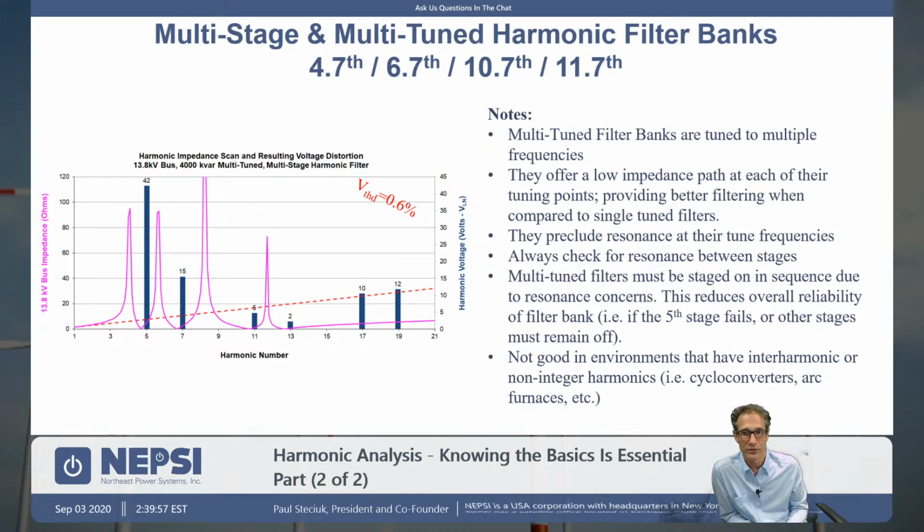It's important that you design reliable lower frequency filters because the loss of one of those could result in the complete shutdown of the harmonic filter. And the other thing is, if you're a filter design engineer, your desire should be, I want to design a harmonic filter using one tuning point first. That would be my recommendation because you're looking to build a most reliable or more reliable design.